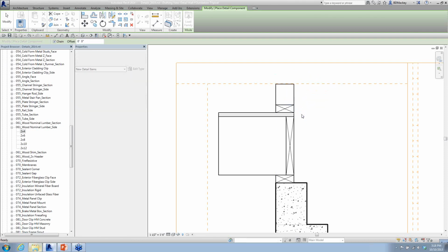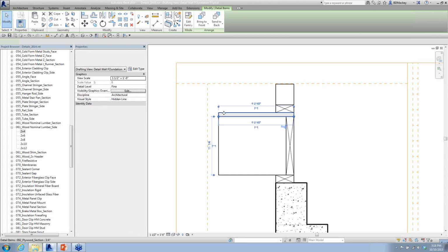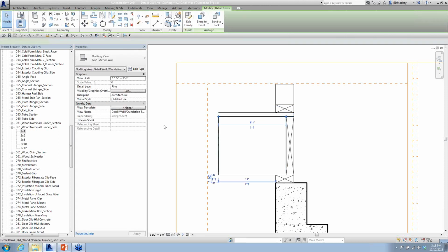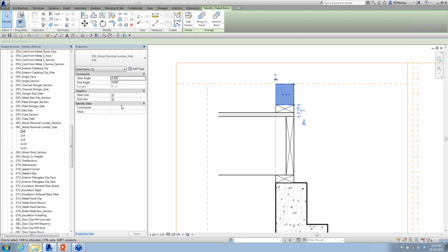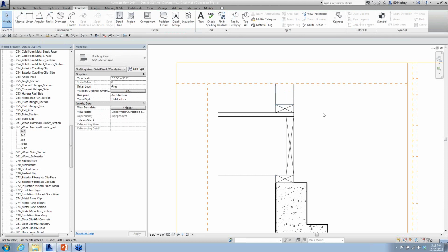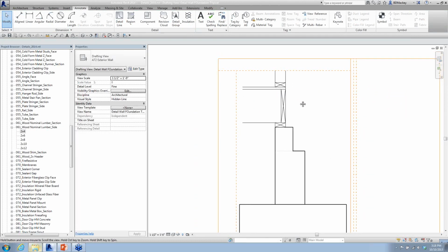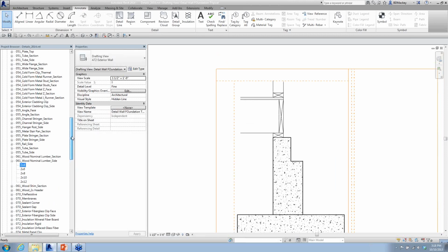Now, the other thing you'll start to see that I build into a lot of the families when I get inside of here is I'm not a big person on going in and putting break lines in all over the place. If you use break lines, that's great. You can use them. But for me, this is the other way. I turn off those extension lines. So I can just come in here and turn the end line off of these. And as I turn that end line off, now I don't have to worry about going back and putting a break line where I might need it. I can just turn the end lines off and it's kind of looking like that detail's going through. So I've got that. We're going to go ahead and do some sheathing. So we'll find our sheathing inside of here.